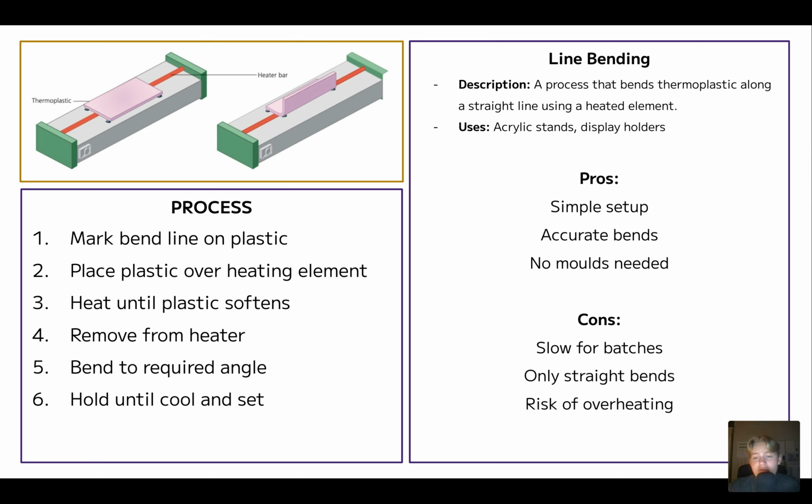The cons of it, however, is that it is quite slow because you obviously have to wait for that material to heat up, and also it's kind of a manual process. You also bear the risk of overheating the material and potentially melting it into the heating bar, or burning the surface of the material. Can happen with acrylic as well.